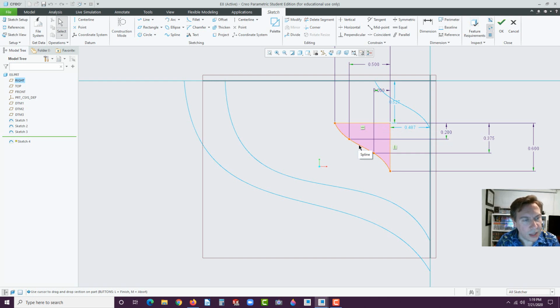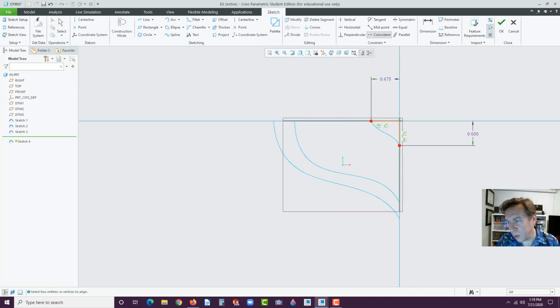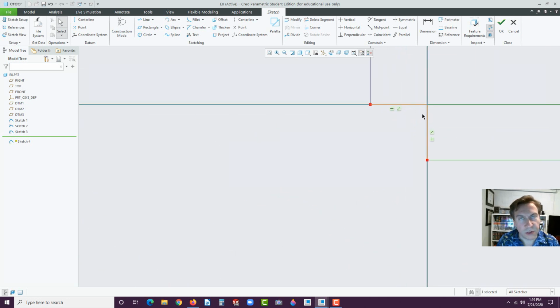First of all, you could click on this line and delete it. We're going to put our own in just a little bit. And I'll go to coincident, select this line to that, and then this line to that. And let's make those smaller. So this one is going to get really tiny. They're going to be 0.01 for each of those dimensions. So here, middle click, 0.01 and 0.01. And let's zoom up there. Just scroll with your pointer over that region.